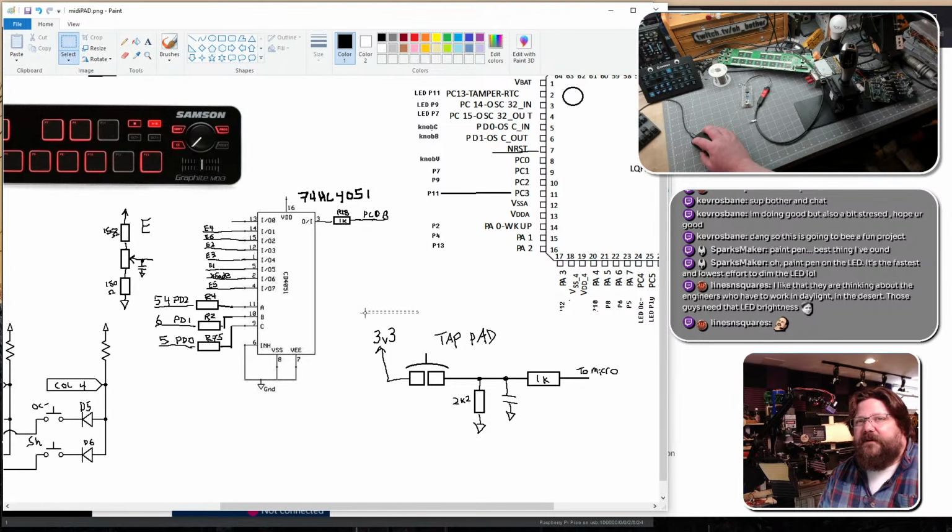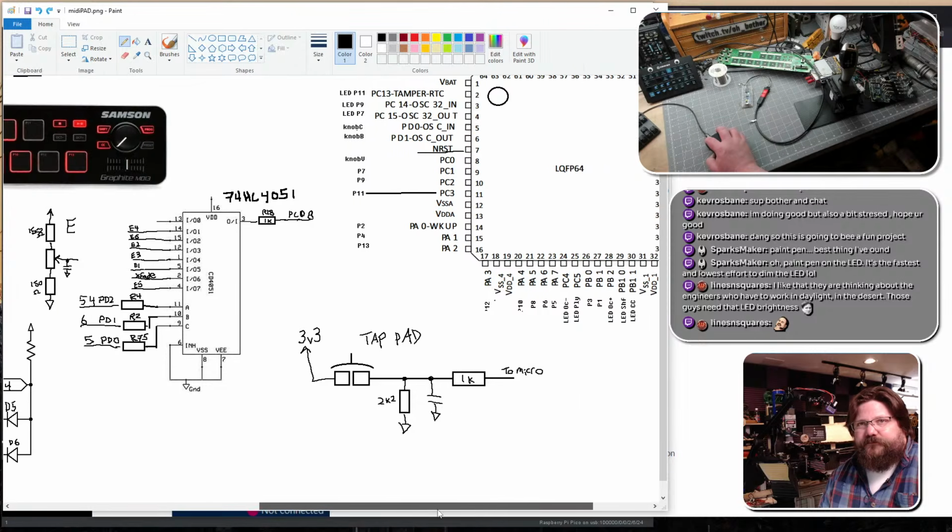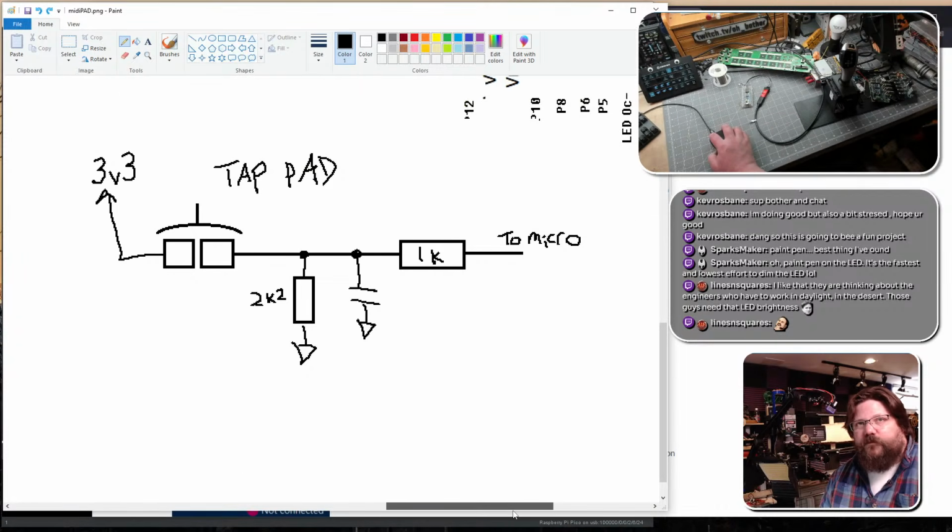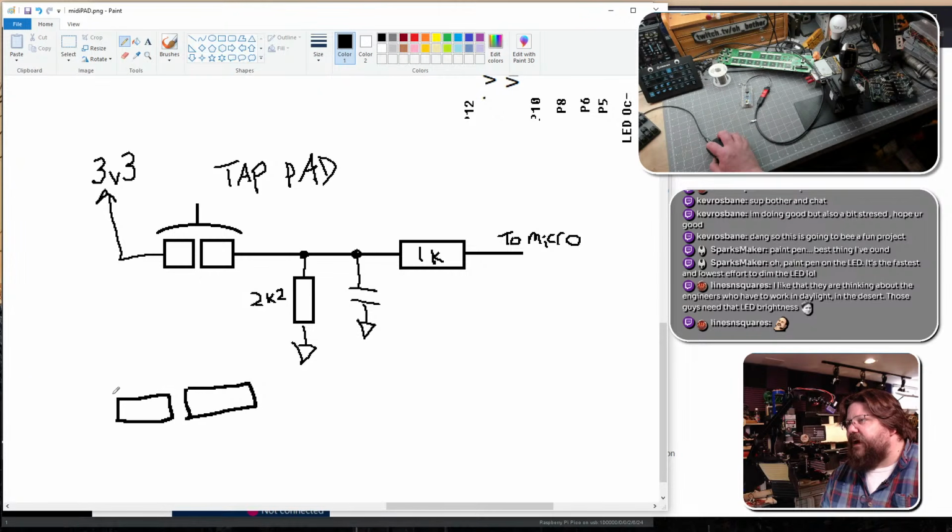The only thing that maybe they're not really doing in Arduino libraries is these types of tap pads. The tap pad is fairly interesting because it uses a concave button in order to short out a resistive material. Now I'm drawing resistors as boxes, otherwise you get this for a resistor. So what basically happens is that thing makes initial contact, right? Time is equal to 0, nothing has happened. You've got two pads here. This thing is not connecting them. You have infinite resistance, so there is no positive power on this part of the circuit, right?